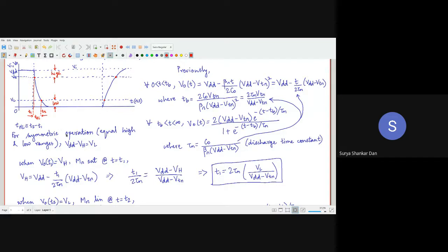So like these variations, if they are less, then the noise margin will be higher. So in our discussion, remember we had this, no? VO, this will be VDD. Yeah, as you can see, this is VDD and this is our zero. Correct? Everyone, listen carefully. All I'm suggesting is this VO from here to here, VH, we will consider as logic high. And the VO less than this is logic low.